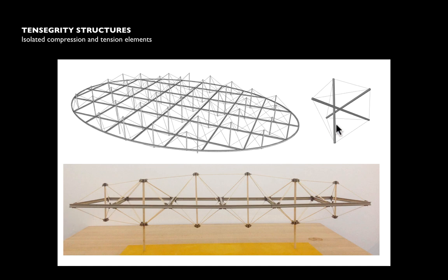And then here, Kenneth Snelson, who was a student of Bucky Fuller's and came up with this principle, made a career of designing sculptures that use the tensegrity principle. So here is one module where three compression elements are connected by cables that triangulate them in space. So their ends are all fixed relative to one another, and this becomes a three-dimensional truss where all of those triangles are stable, and therefore the overall form is stable. Even though to our eyes it looks like these three sticks might fall down at any minute, each of their ends are stabilized relative to one another.